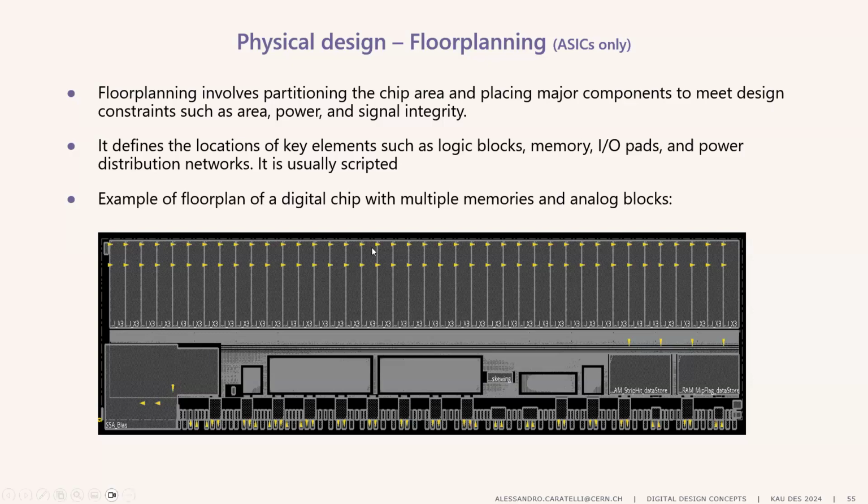Like here in this case, this is a real chip that I'm showing here. Here I placed some memories in this part, some analog blocks here on top. Here are some other digital blocks. Here I have some DRAM, some SRAMs and so on. Here I have some IO pads, and all the gray, all the rest in the middle is digital standard cells, which are very small and spread around. But basically, it means to define the physical layout of the chip.